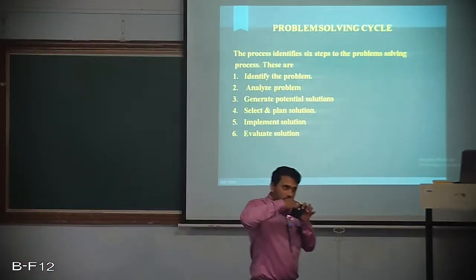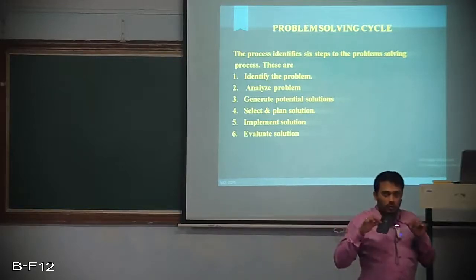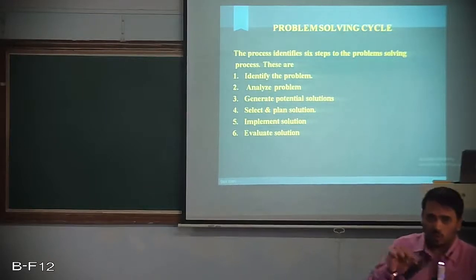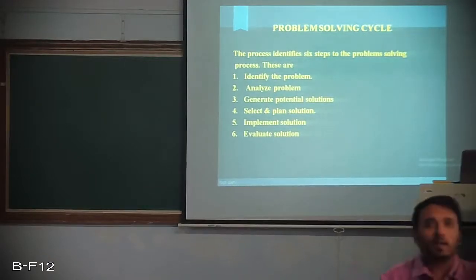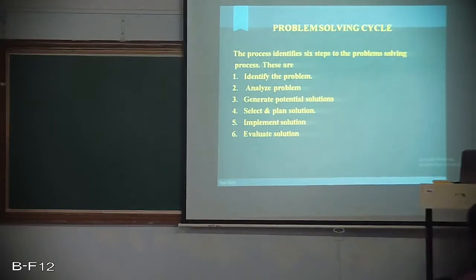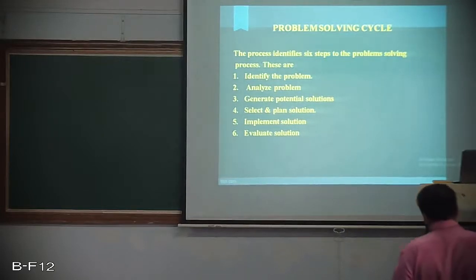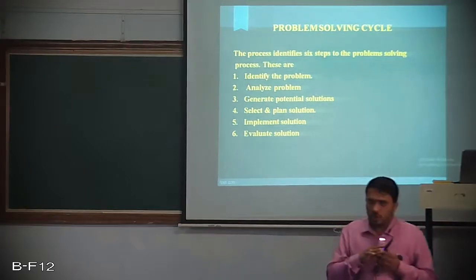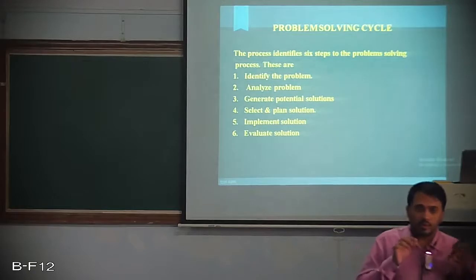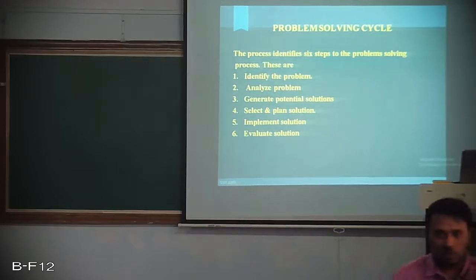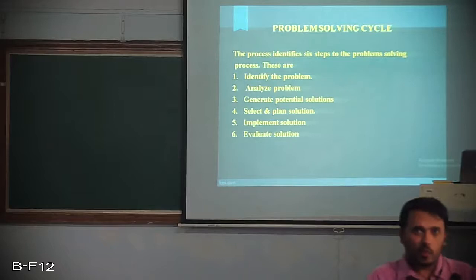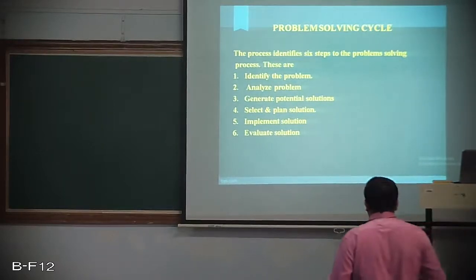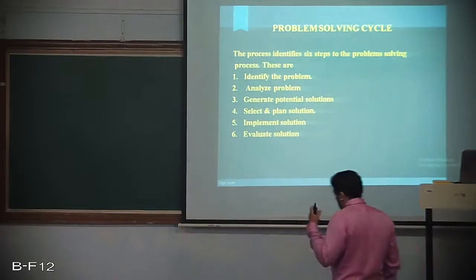And whether the thickness of the cell phone has also been changed. If it is changed, up to what thickness it has been changed, and what tolerance I need to provide so that it can easily fit and can be easily removed from the back case. And with respect to this logo, whether the logo position has been changed or it is the same, and whether the size of the logo is the same or has been changed, with respect to that I am going to provide a cutout over here. All these things happen in analyzing the problem.